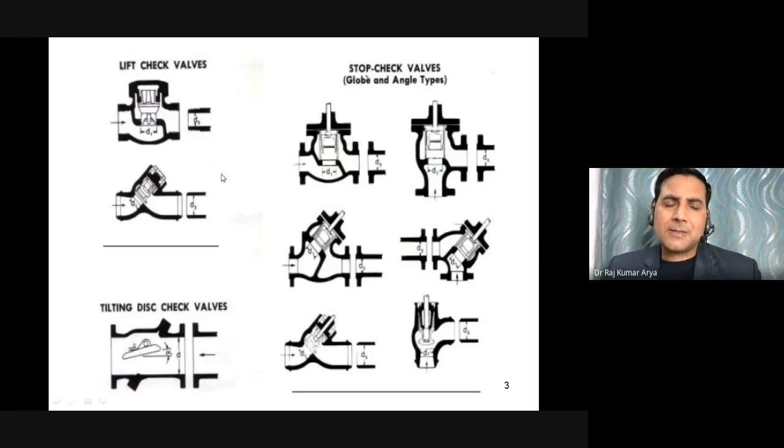Now this is actually again another type of valve. A lift check valve here. So a lift check valve is something where you are not allowing backflow. The check valve's purpose is just to stop your backflow actually. It only permits forward flow and no backflow. In this case, if by chance the pressure is high, this will push this particular lift upside, and fluid will come out from here. As soon as the pressure at this end decreases, this lift will bend down, and finally your flow would close.